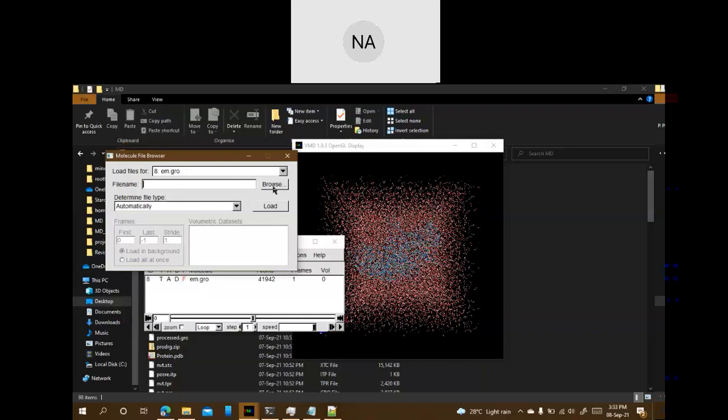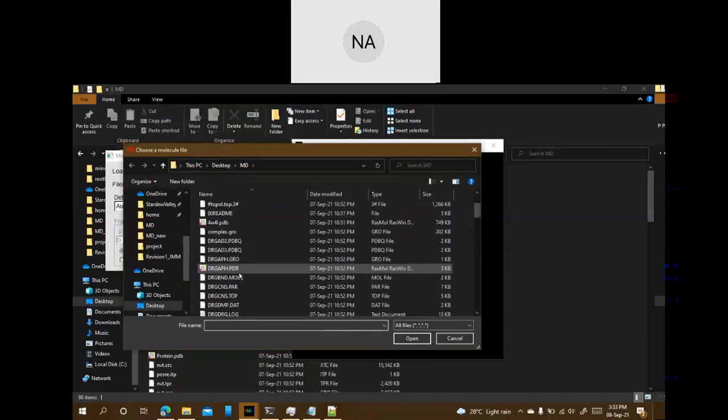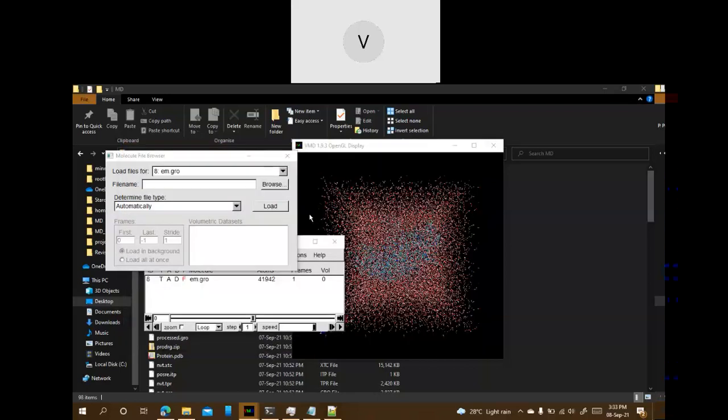So this step, we'll be loading the trajectory file into the molecule. Stride is like you specify which frames to load. If you specify to load everything, all the frames, it could take a lot of time and memory, and needs to be done on a high-end, high-spec workstation laptop. You can just load every 10th frame over here.